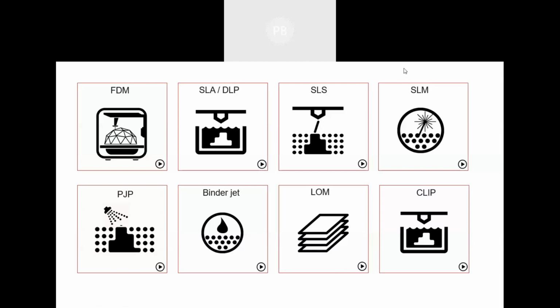Then after that there is SLS. SLS is another technology where we use selective laser sintering. Here there is a powder form of material which is sintered by a laser. Sinter means it gets fused: the powder gets slightly melted, and the next powder gets melted, and the powder particles get joined easily, by which the product is formed. These kinds of materials provide isotropic properties. Here you don't need to worry about the layers. It provides isotropic properties due to the fusion or the sintering.